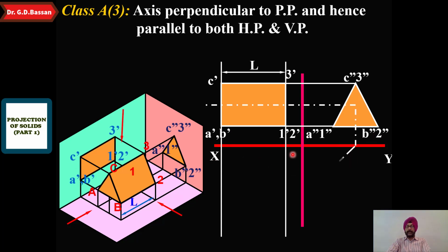So from here, this is the axis which we are projecting here. This is the one end which we project here on the XY line. Draw a 45-degree line to project it onto the other axis which is X1, Y1, and you get the projection on the top view. Then the third point, this is the A point. So A will be here. B, when you see from the top, you are getting B here, and one point will be on this opposite side.